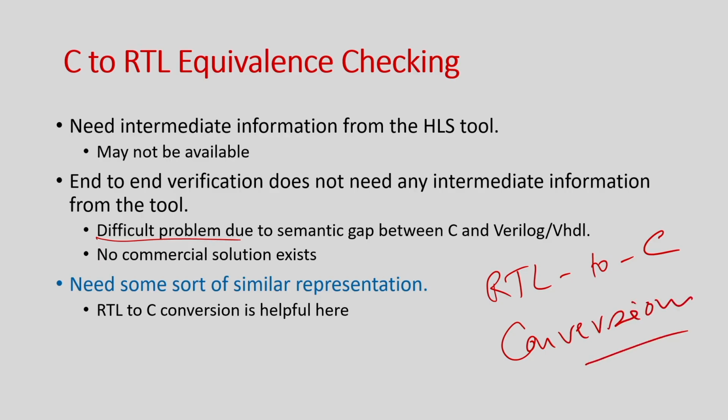I hope you remember that. Specifically, the RTL that is generated by the high level synthesis tool has a very specific structure that I have talked about: it has a data path and a controller. By analyzing the data path for each controller signal, each in-state controller assignment, we can extract the operation that is happening in the data path, and this way the controller FSM converts into an FSMD, and our program model is FSMD, right.